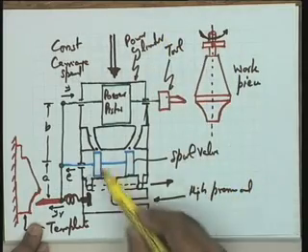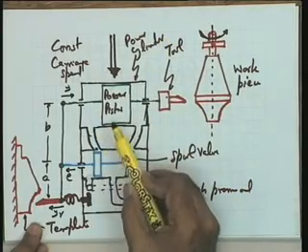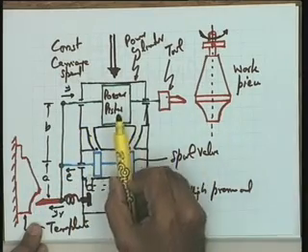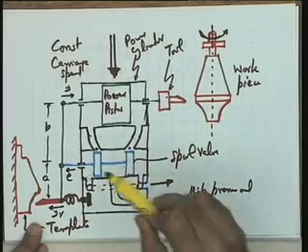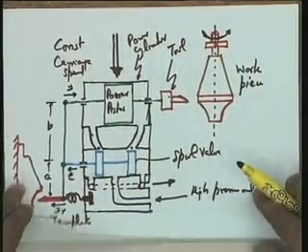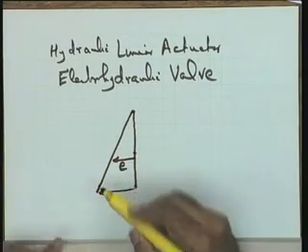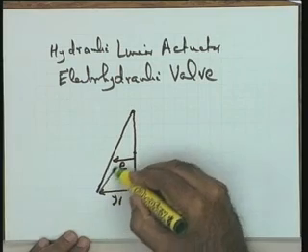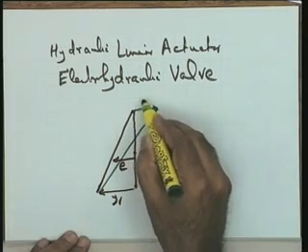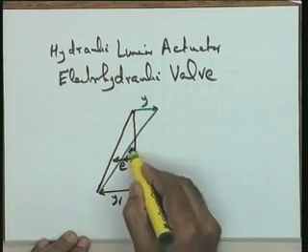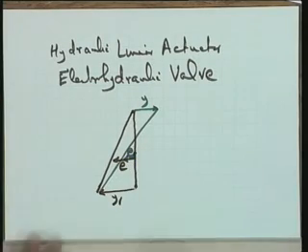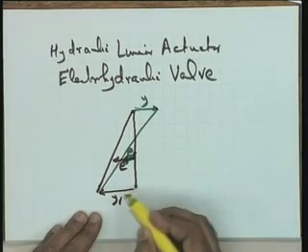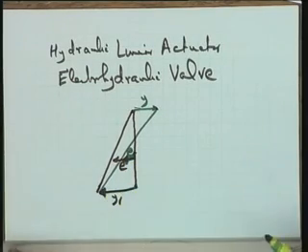So, if the high pressure oil rushes to this particular power cylinder, the power piston will move to the right, and hence a new equilibrium position will come where the forces will balance. And let me assume that the new equilibrium position is given by this diagram of the power piston, this diagram of this particular position of the lever. So, you can see that this is the net position. Y is going to move by this amount, E is going to move by this amount when YR is the input to the system by this amount.